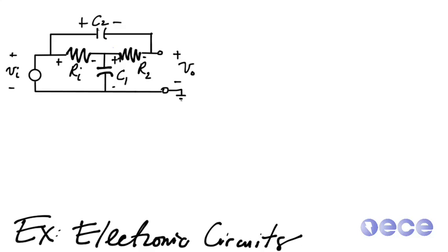We can call that R sub I, actually. Then we have two capacitors, C1 and C2. I'm interested in measuring the output voltage, V sub O. So with these values, we can label our important nodes, A and B. So we're going to use A and B in terms of defining voltages with respect to ground, so that we can use the differences in those voltages and the components through which they flow to estimate current, according to the equations of motion.